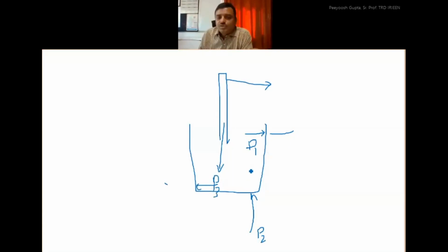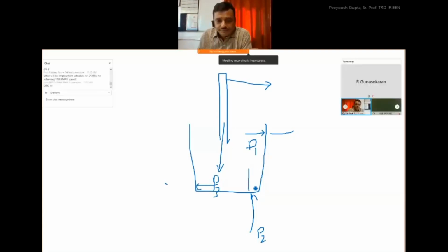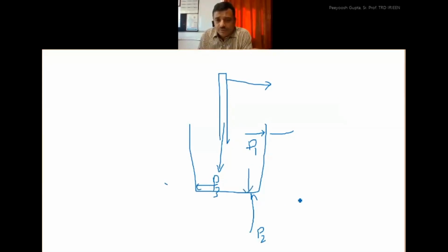basically the foundation will be forcing from top to bottom, and an equal force from the soil is also required. So soil bearing capacity should be matched, and we see that if these P1, P2, P3 forces are within the soil bearing capacity, our foundation is okay. And there is one more test for the foundation. If we divide this foundation into 3 equal portions, and the resultant passes through the middle third, our foundation is supposed to be okay.